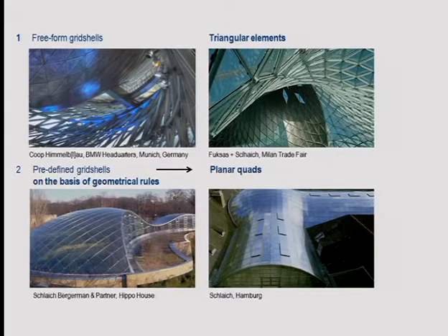All right, let's go back to the slides. I want to show you one last problem you can solve by means of optimization, and then I'll let you go. The problem is called planarity. Why planarity? You remember before we spoke about the idea of triangulation. Of course, you can triangulate any type of form, so you can discretize something continuous. But if I want to realize something like that, this one at the bottom, you see there are quads. Bracing is done by means of steel wires, so there are no triangles. And how can I make sure that these quads are actually planar?